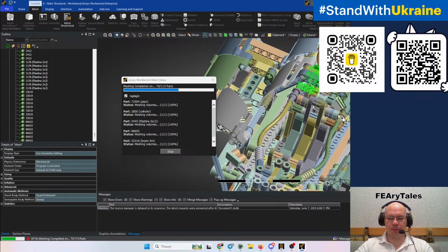Not the virtual cores, not the threads, but the physical cores from the processor. So I have 6 cores. In most cases, Ansys will use only 4 cores with the default license, and for additional cores you need an HPC pack.